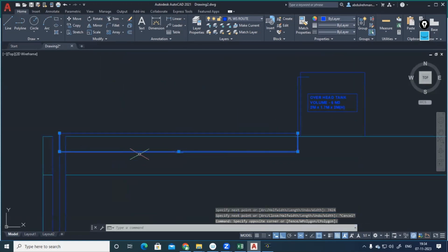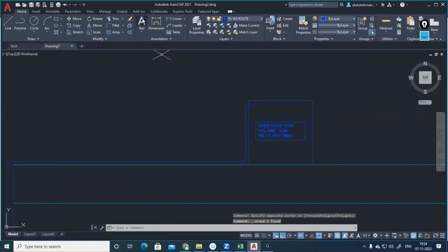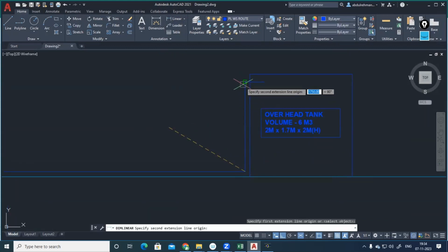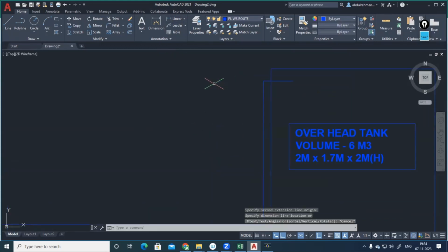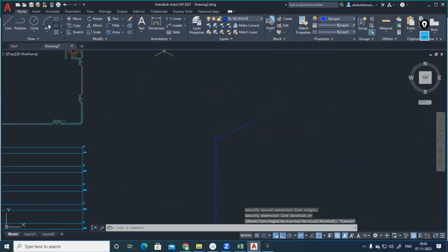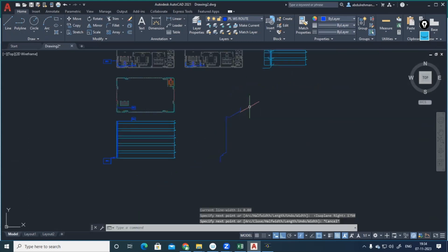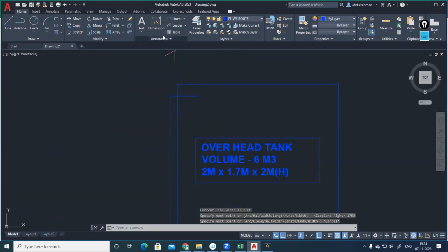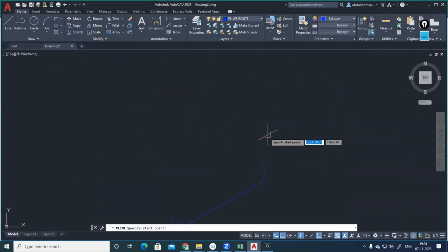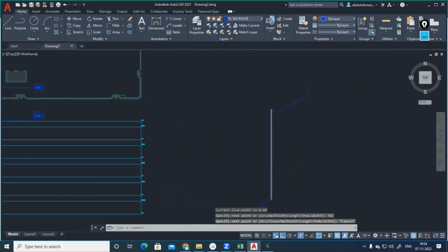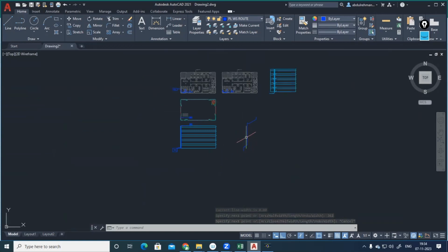Now it has reached just to bottom of tank. Now it has to vertically rise upside. From this point, vertically it has to rise upside 1750. So from here, 1750, then it is reaching to the tank, this line. See how much it can come. 362 millimeter. So from there, that will be 362 millimeter. This is my isometric route.